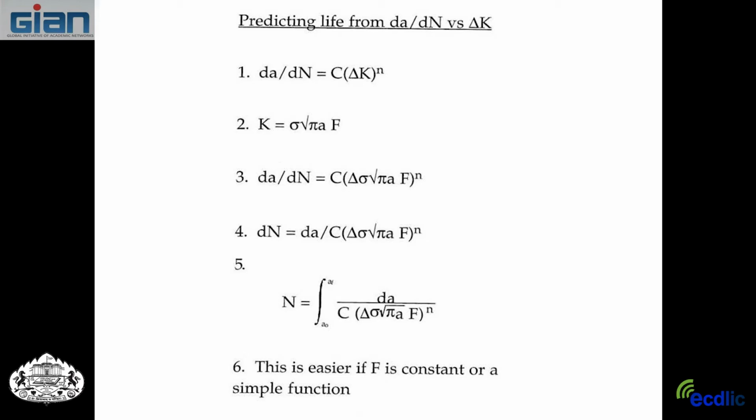Now, initial crack size, usually you have to pick a value. And the way it's often picked is to talk to non-destructive evaluation people and say, if you were going to study or look at the structure with your non-destructive tools, how big a defect could you miss? Not how big can you find, but what might you miss?